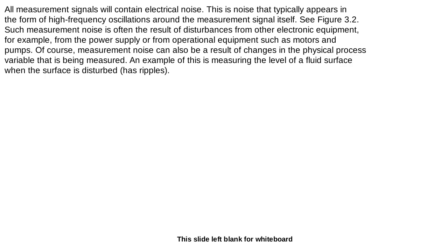A low pass filter works by allowing all energy that lies below a certain frequency, and that certain frequency can be called a cutoff frequency, to pass the filter unhindered. Whereas energy that is above that cutoff frequency is reduced in strength.